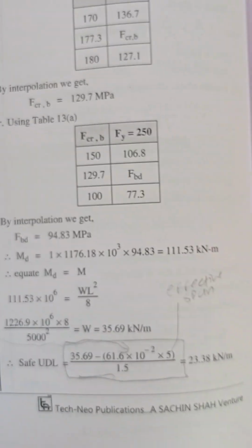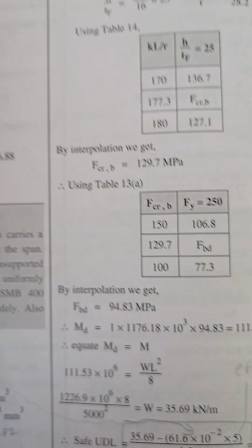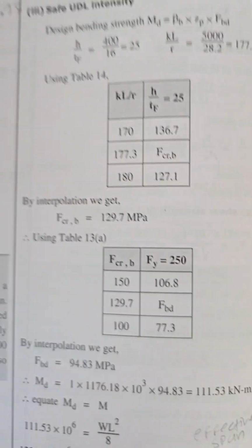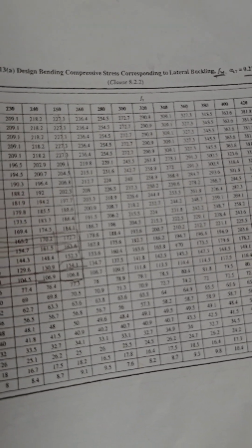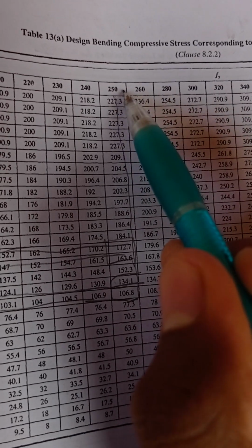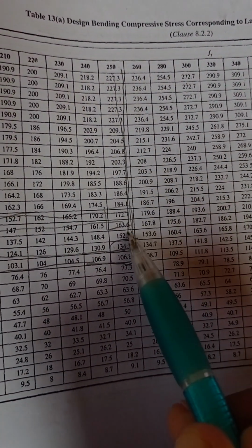Go to table number 13A in the IS code, which is after page number 54. From there you can find the Fy. If you don't have Fy given, just assume it as 250. So we assume it as 250. Then, just drawing a line,